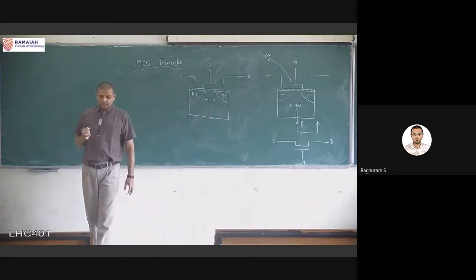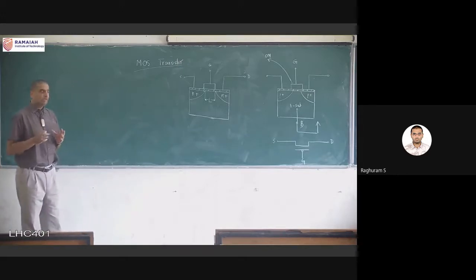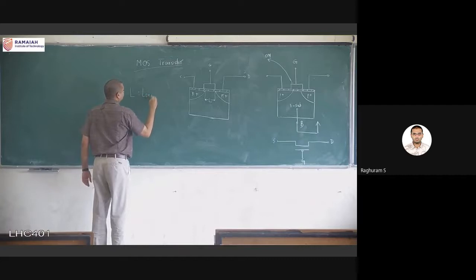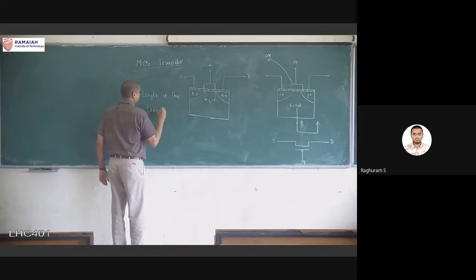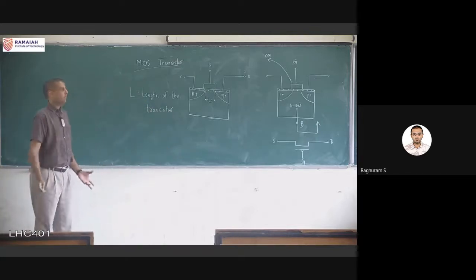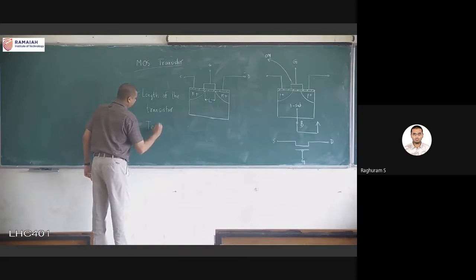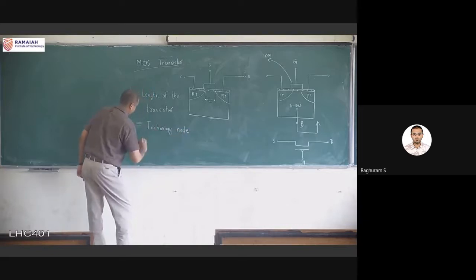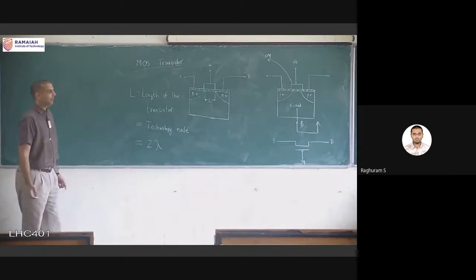This part is very important. This particular dimension, which is always represented as capital L, is the length of the transistor. This is a very important definition for many reasons, because this is also the technology node. We discussed this in the previous unit.